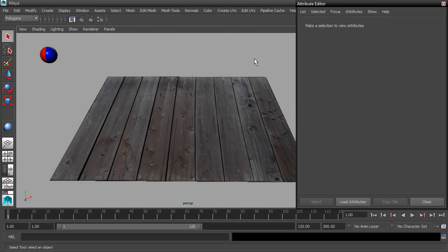To make the ball look like shiny reflective plastic, we need to have some kind of environment for it to reflect. And an easy way to do that is to create a sphere and place an image on that sphere. And that will be a simple fake environment that will appear in reflections.